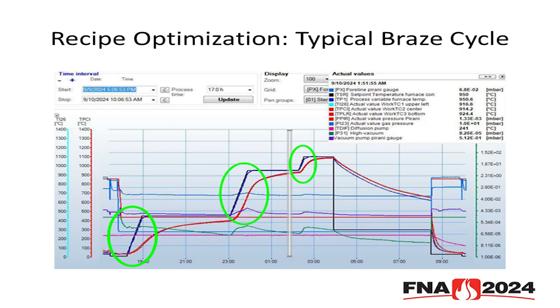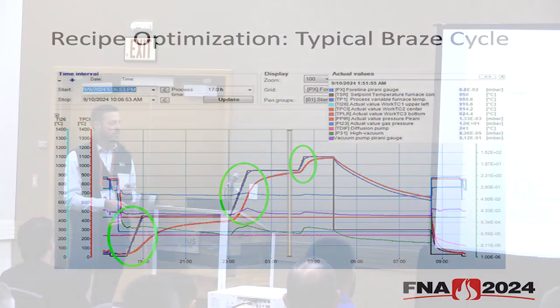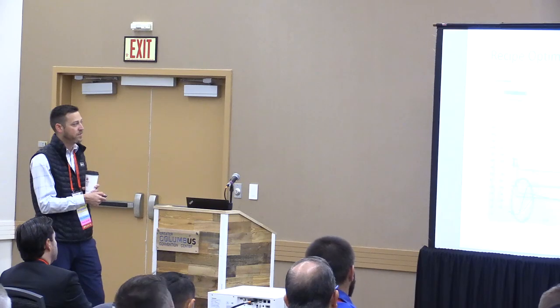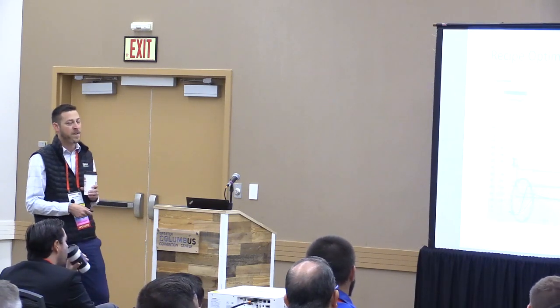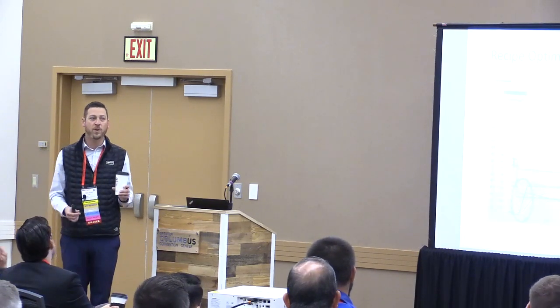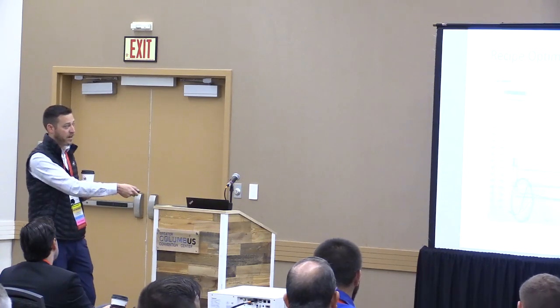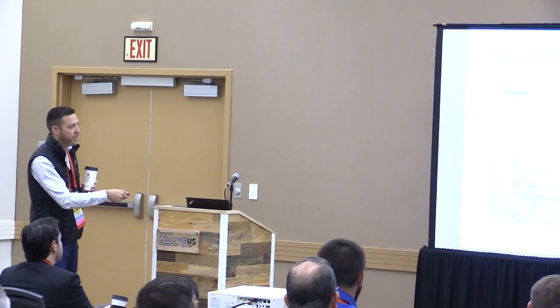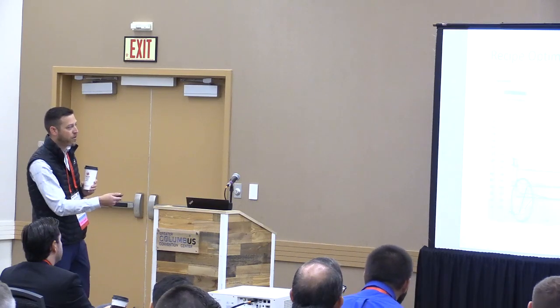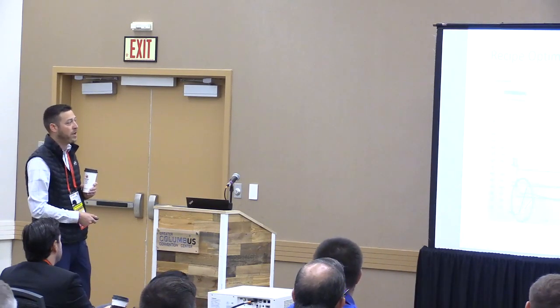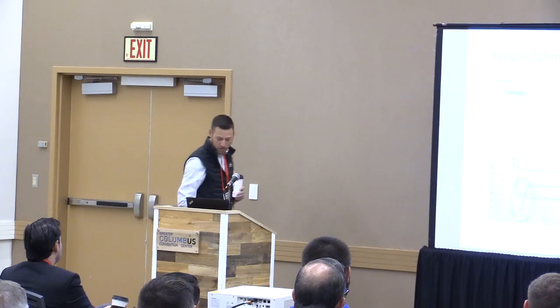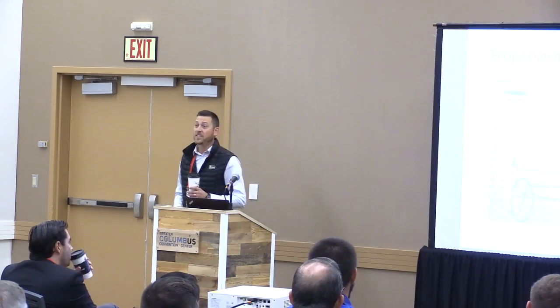that final critical soak. And then the next thing I'll draw your attention to is they're going into a vacuum cool. And this is real common in a lot of brazing applications where the braze is wet, and now we don't want to blow it around with a force cool. We want to do a little bit of vacuum cool and let the braze solidify before we go into an actual quench, which you're seeing right here. But in this case, they're going 4 hours of vacuum cool, and they're vacuum cooling down to, I have the temperature here, down to 1,200 degrees from 2,000 degrees. So that's a very long time. The braze is definitely solidified at that point.